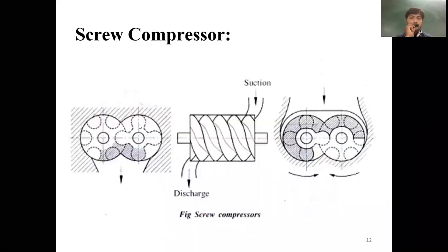Okay, this is a screw type of compressor. Basically, this is like a gear. Gears are attached and in motion. So refrigerant gases are trapped inside this chamber, and after motion, high pressure is discharged. Okay, suction from here, suction of refrigerant in the form of vapor, and high pressure refrigerant will discharge through this one. This is connected to the motor. Here, 2 rotors in the form of gears are attached to each other. Okay, this is a screw type of compressor.